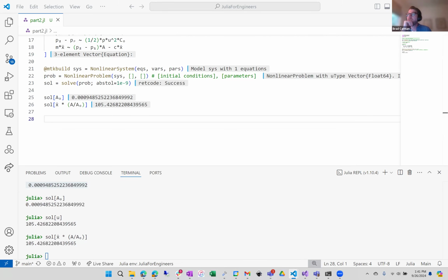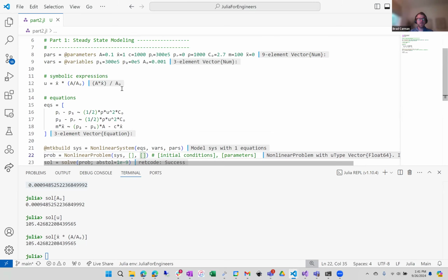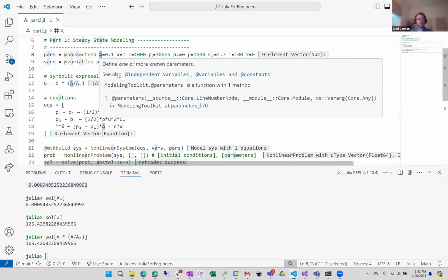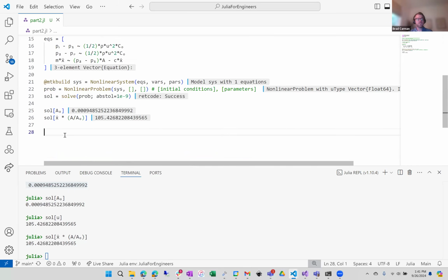Okay, so there's a question. Since you're able to change parameters, can you change the parameter index by parameter? Yes. As you can see, when I was building the nonlinear problem, you can symbolically change your parameters there. You don't have to index the parameters. You just type the symbolic term. And as we move later into component-based systems, you can index using namespaces.